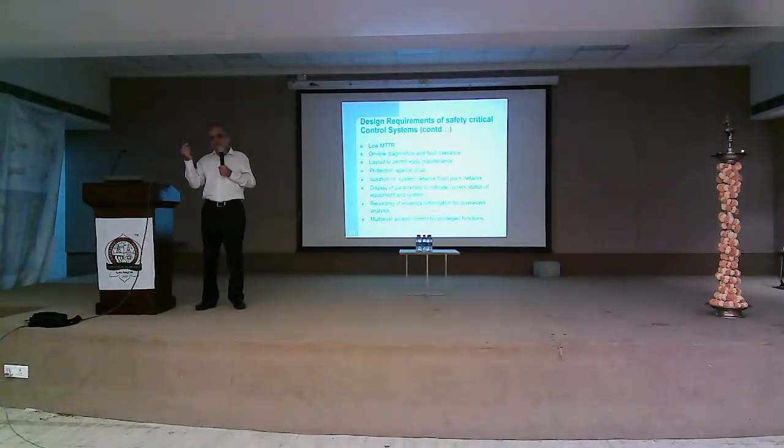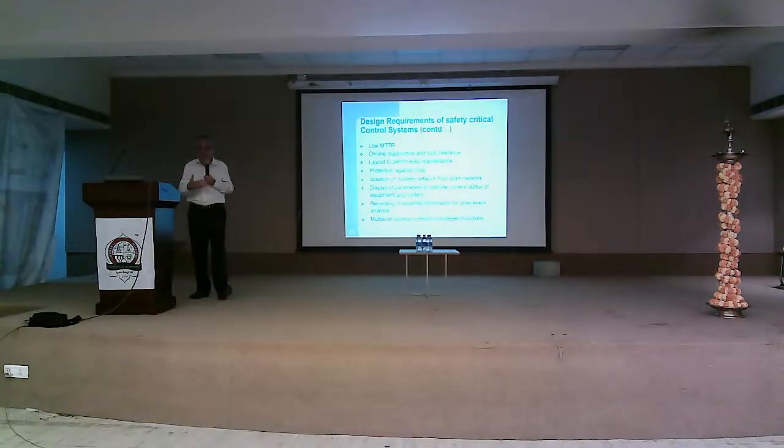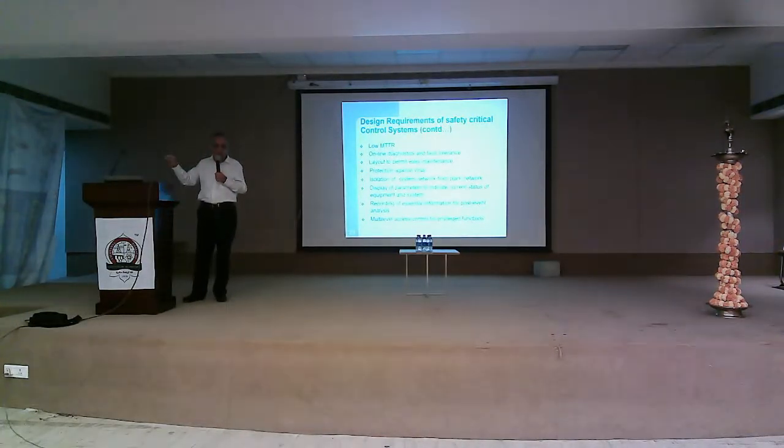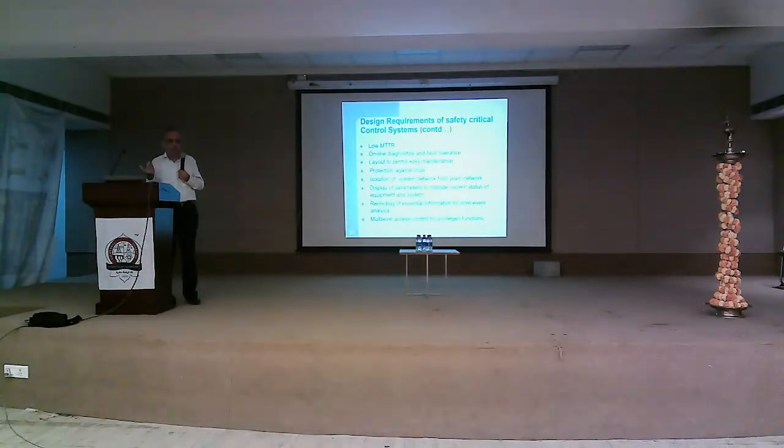For analog output, which is normally 4 to 20 milliampere, we feed back all the outputs to one of the channels of the ADC. One separate port is used for that purpose. And we see whether what we have output is really right. If it's not, we know the port is faulty. So this online diagnostic becomes very important to achieve low MTTR and hence high availability.